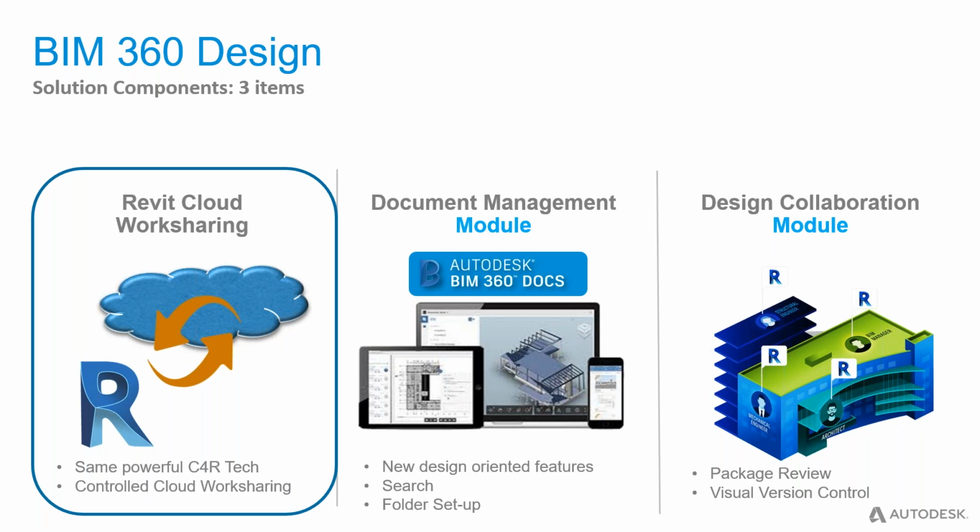I tend to say if an IT manager would in the background remove Revit Server and put the central files on BIM 360 Docs and Design and give everyone a local copy in the weekend, and Monday morning they start again. If they don't look at where they're saving to, they wouldn't know there's a change actually. So that's how easy this is to implement, if you will. So Revit Cloud Work Sharing, still the same philosophy for all of those architectural designers, structural designers, etc.